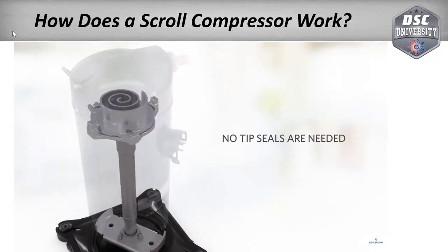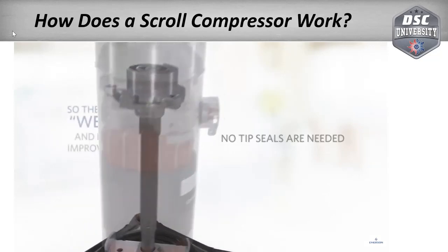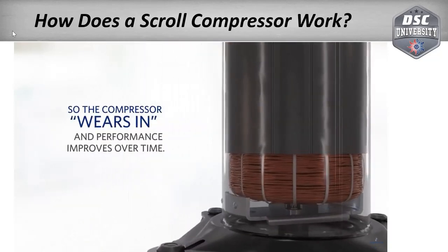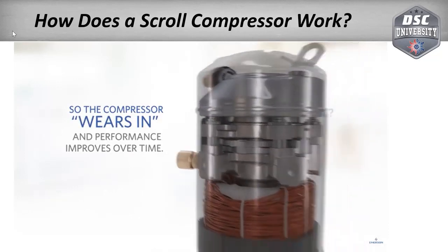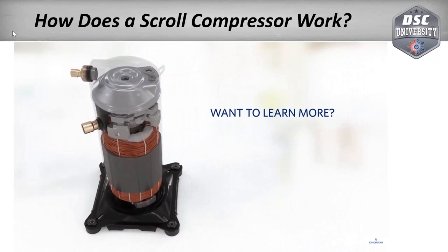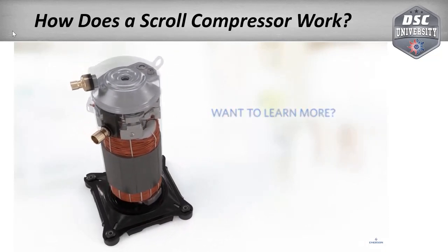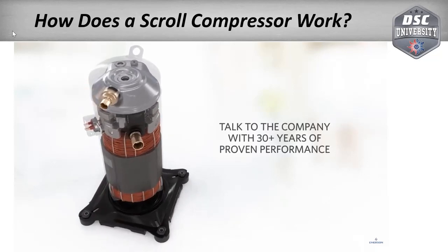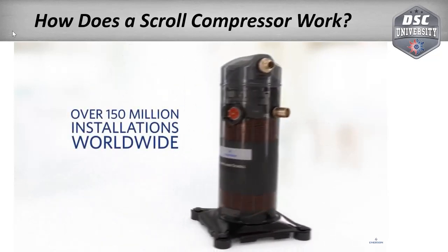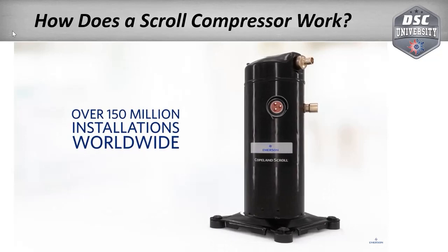I actually thought that it bumped up and down a small distance. No. So you see the whole bottom 2/3 of that compressor is all motor, and it's just turning a shaft. So you really only have a couple of moving parts. You have the shaft of the motor, and you have that one scroll plate. That's all that's really moving in there.